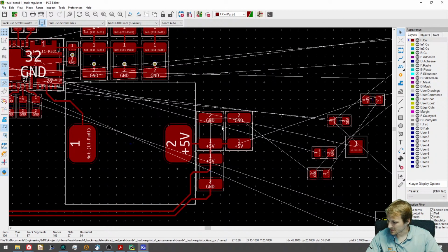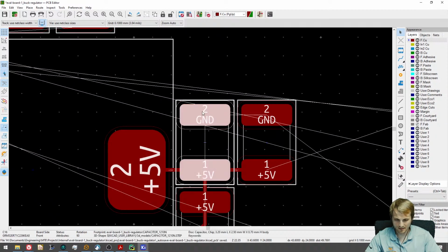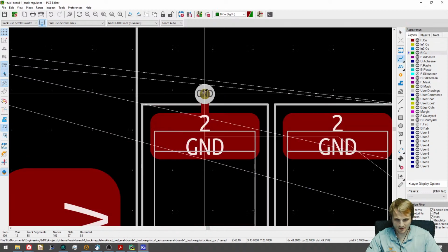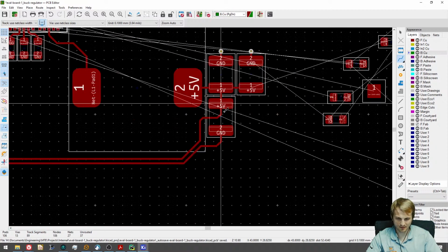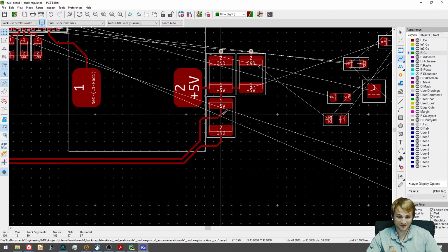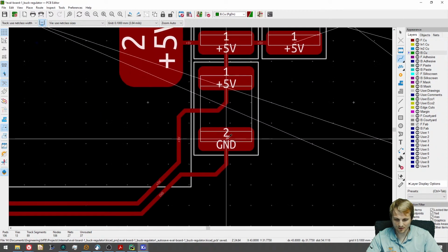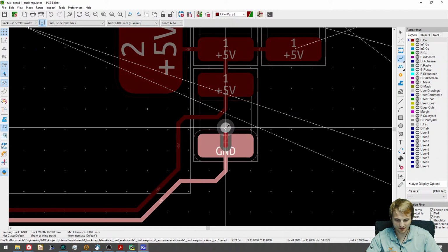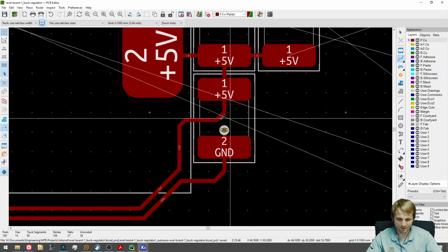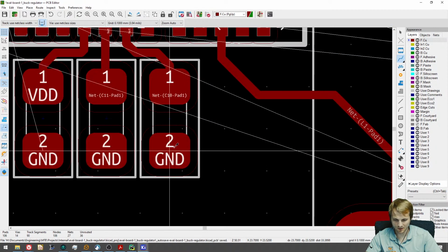So the layers are to separate some of the signal lines, not to introduce crosstalk. Yes, that is one reason. The other reason that it's really good to have signal, ground, signal, or signal, ground, ground, signal is it's really, really nice not having to worry about having an adjacent reference plane for every signal layer. So by doing it like this, every one of your signals is adjacent to a ground return, which is one of the main goals with any stack up.